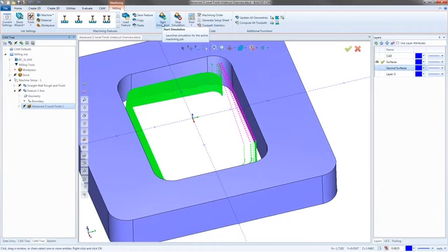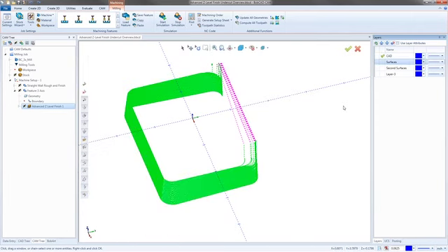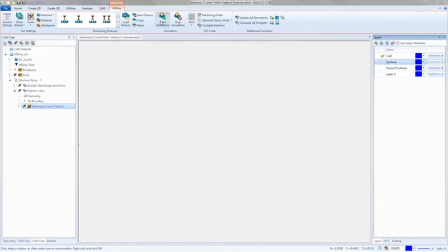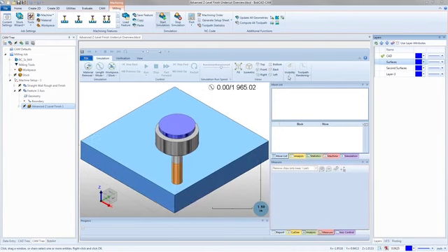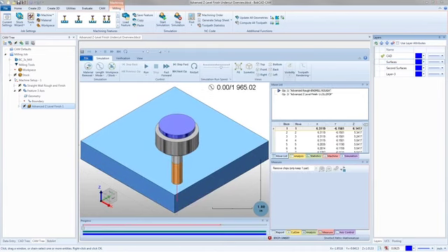So I'm going to go ahead and launch my simulation. Let me do this first. If you want your simulation to load faster, you turn off the solid, and it'll pull everything in faster. In this case, I can turn it off. This will be fine. So this will launch the simulation a little bit quicker, because when you have a solid model on inside your CAD window, it unlocks the ability to show a workpiece under the visibility tab here. And without a solid model on inside the CAD window, you don't get a workpiece. So if you leave it off, no workpiece, which means we don't have to try and pull a copy of your model into the simulation to make a workpiece. So it loads a little bit quicker for you.